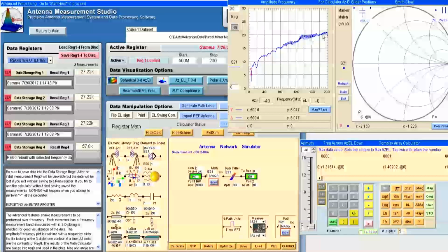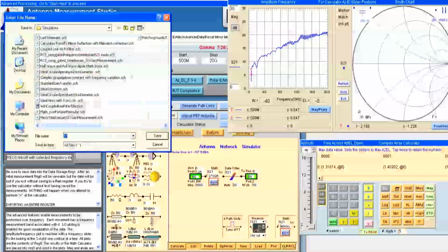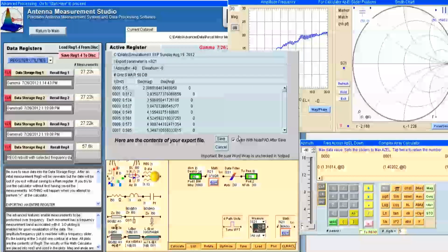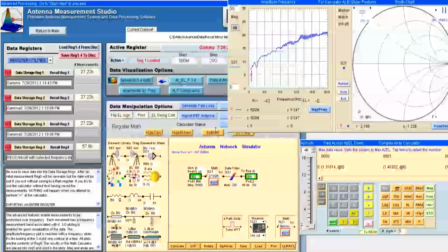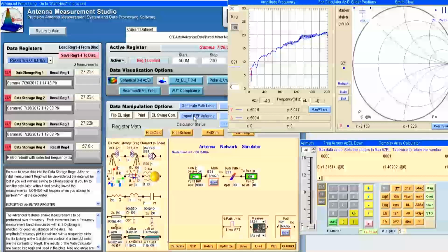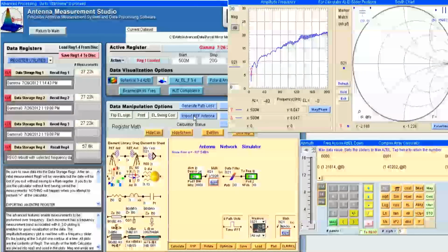If we wish to use this data and other antenna measurements as a reference, we could export this data as a .s1p file in dB format. An S1P file can be processed in the reference horn section. This enables your own calibrations in your own reference antennas, be it narrowband, broadband, a few data points, or even just a single data point.